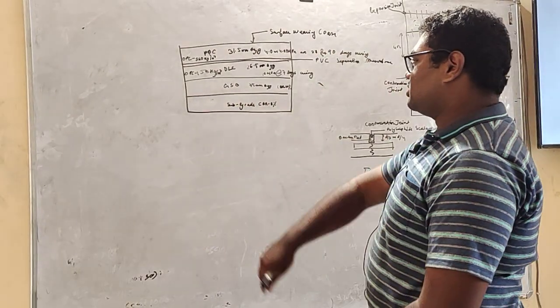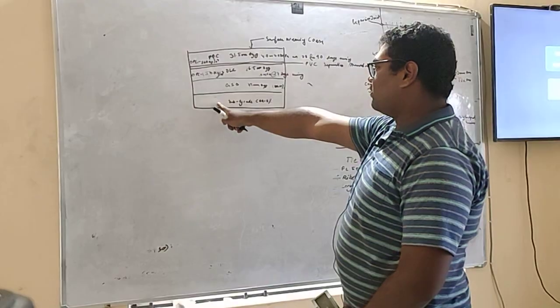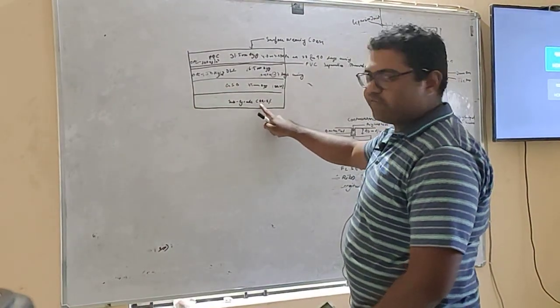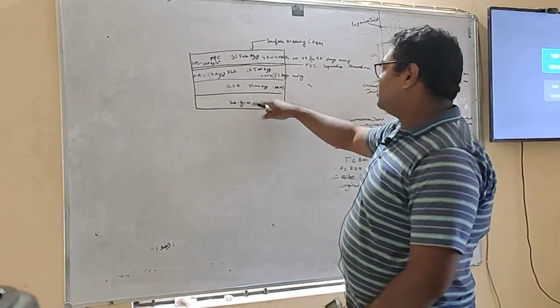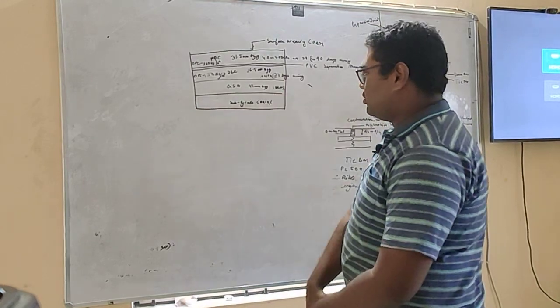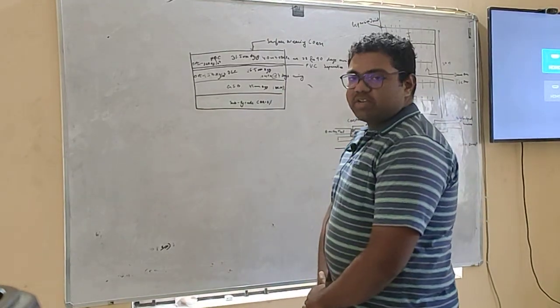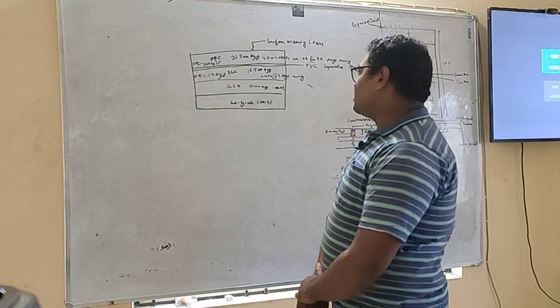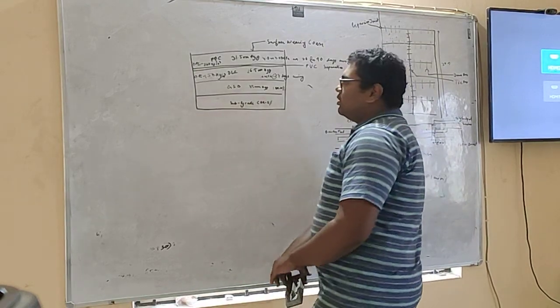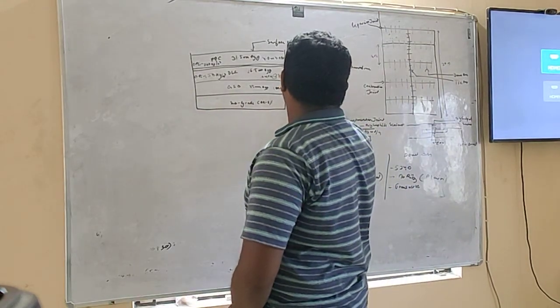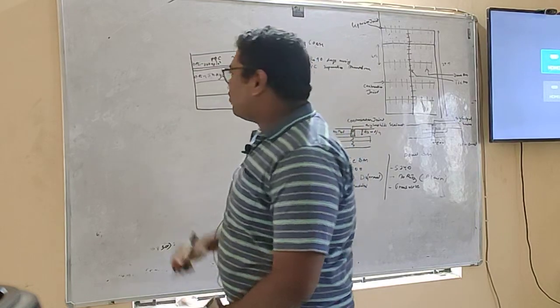So the subgrade of rigid pavement must have a CBR value of 8%. Then the GSB, or granular subbase, must have an aggregate of 75 mm and a CBR of 30%. Now we will move to DLC or dry lean concrete.